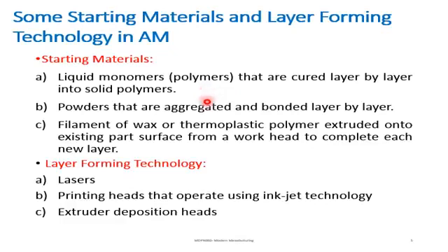The second material could be powder, which is aggregated and bonded layer by layer by a certain adhesive bonding or synthetic binder, and here we usually use printing heads similar to those in inkjet technology.